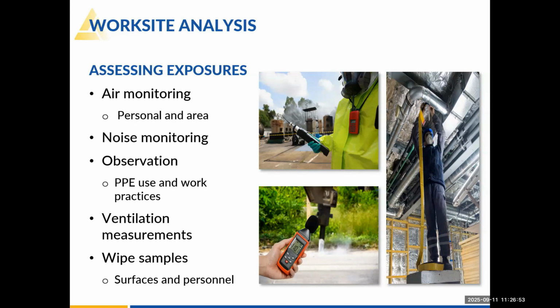And then just a few other things here: observing PPE use and work practices. We can also look at ventilation. So if you have engineering controls built in, an exhaust hood or HVAC systems, or even in a paint booth, you can do measurements to determine if the equipment is operating effectively, just by measuring the airflow and making sure that the contaminants are being taken out of the building. And then lastly, wipe samples. You could do lead or mold wipe samples.